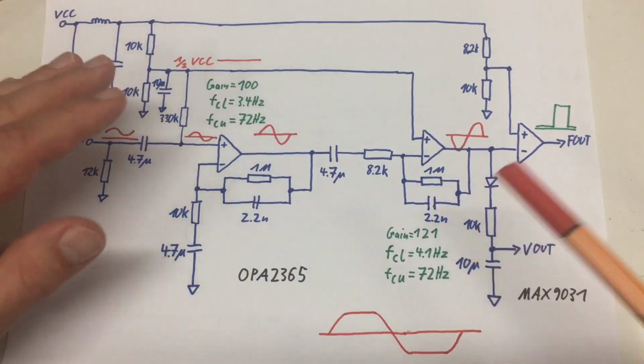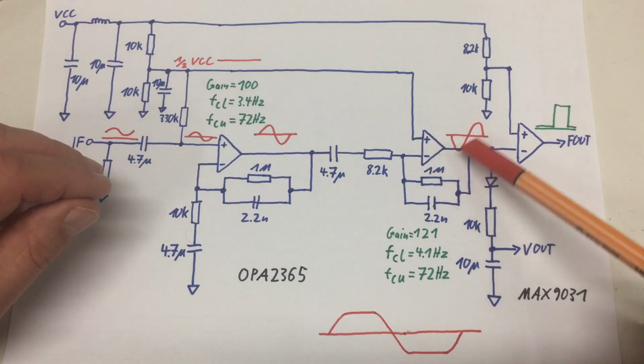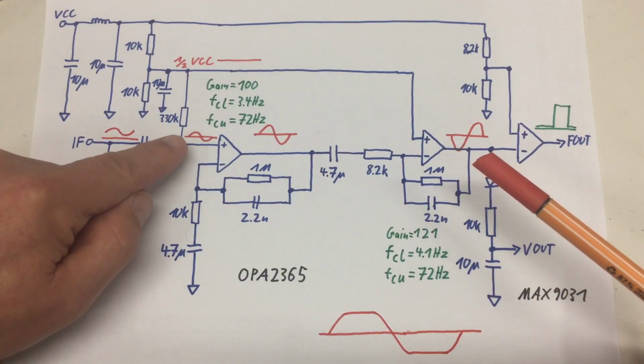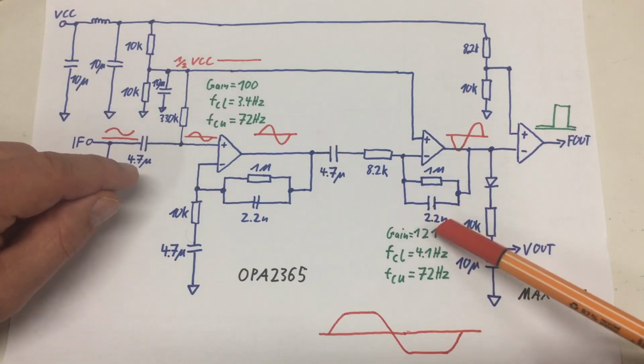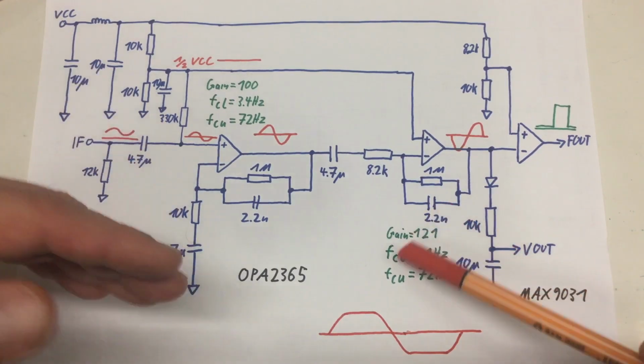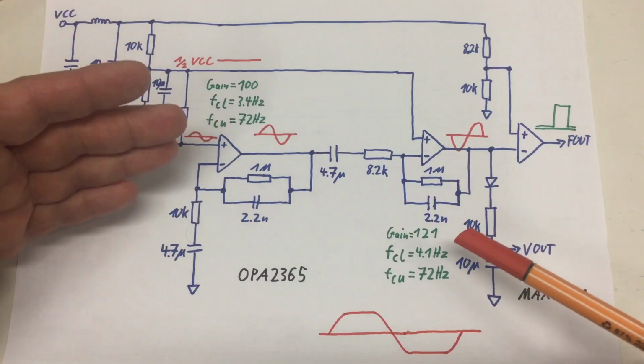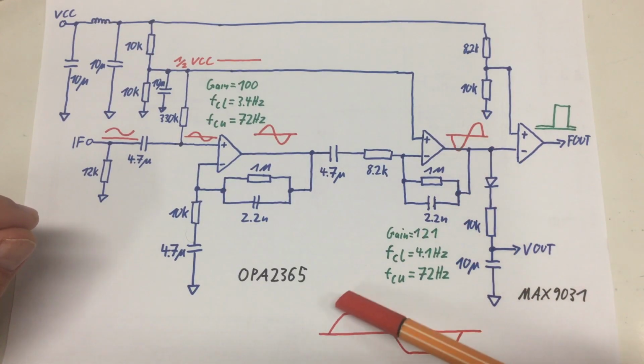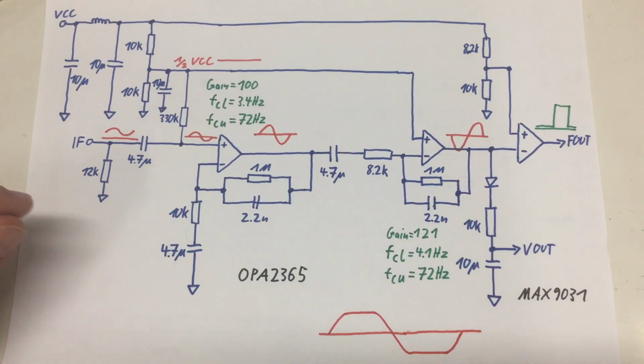Please note that we won't really see a nice sine wave here at that output. If you multiply 1 millivolt by 12,100, you have peak to peak 12 volts. That is, the sine wave form here is probably capped off at 5 volts and ground.